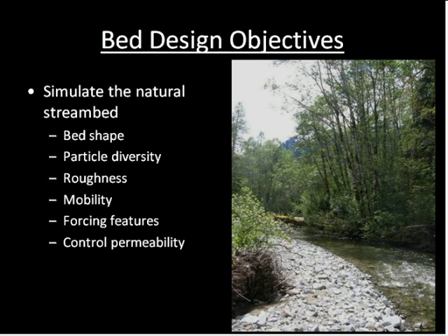You might consider developing your own roughness information if extensive modeling will be used, and that also helps you to gain a bit of insight into stream bed mobility. In addition, it helps to note features that force bed morphology. An important example of this would be boulder forced steps in mountain channels. It also helps to investigate any watershed factors that control permeability or that are maybe a function of site construction activities like compaction or excavation that may interfere with shallow groundwater flow.